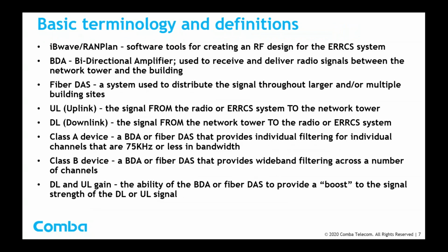I've got a couple of slides here. Just want to quickly run through some basic terminology and definitions because we'll be talking about these things as I go through my presentation. So IBwave or RAN plan, these are software tools that are used for creating an RF design for the ERRCS, or Emergency Responder Radio Communication System. BDA is an acronym for Bidirectional Amplifier. That's a device that's used to receive and deliver radio signals between the network tower and the building. Fiber DAS is like a BDA, except it's a more elaborate system, and it's used to distribute the signal throughout larger and/or multiple building sites.